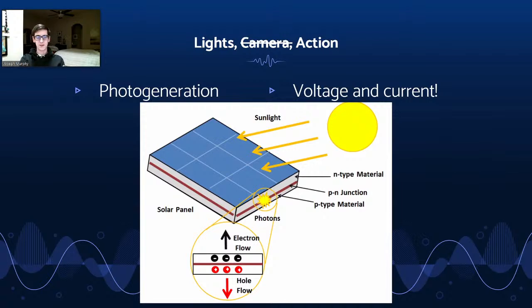we get photons, which, if they have the proper amount of energy, just enough, the same amount of energy as the difference between the energy levels that the electron has to jump. The photon with that much energy hits an electron. The electron absorbs that energy, moves from the valence shell to the conduction band, and now can move freely throughout its semiconductor.